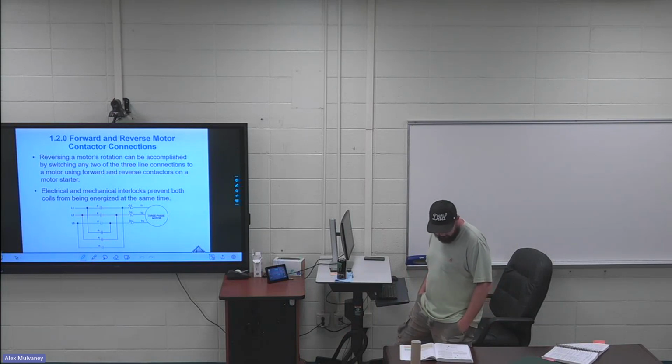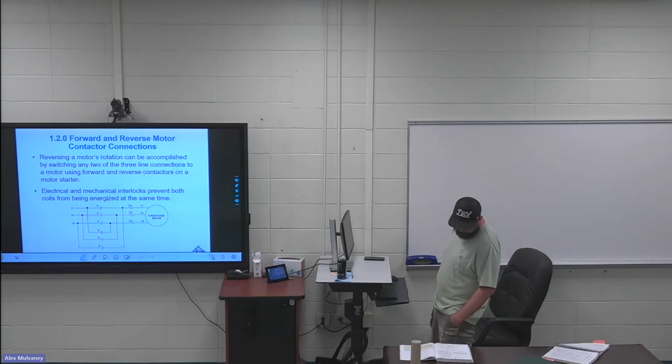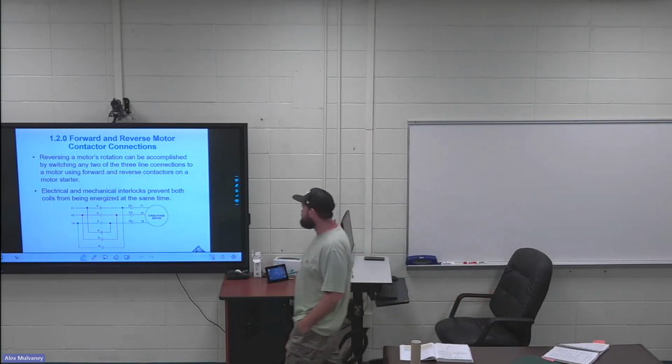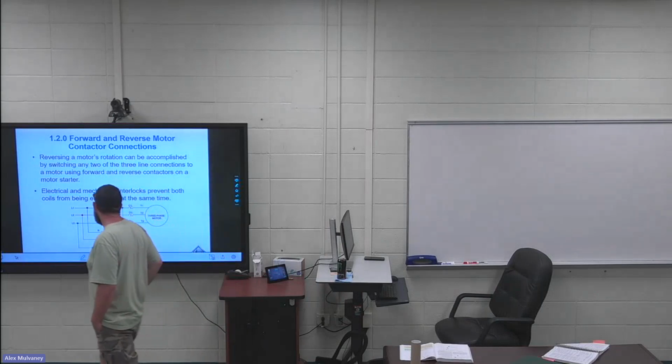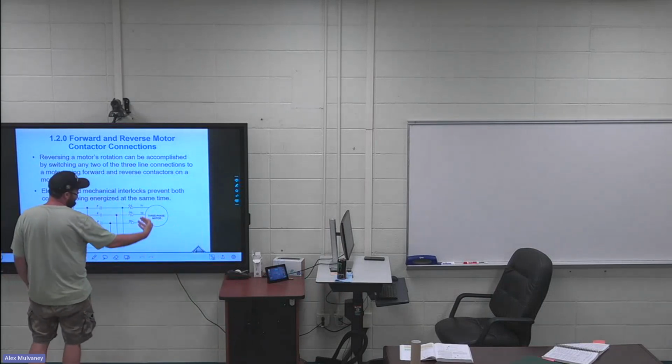When the forward contact is de-energized, the second contactor can be picked up, closing its contacts R, which reconnect the lines to the motor. Note that by running through the reverse contacts, L1 is connected to T3, L3 is connected to T1. The motor will now run in an opposite direction. So, all that to say, whenever you have forward turned on, these three are running forward.